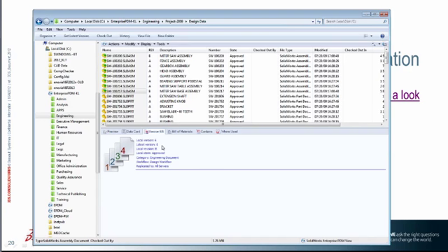The Version tab just gives me some information about what I have in my local cache, because Enterprise PDM works on a local cache basis. What that means is that we have a centralized server where the files are stored, and you can have replicated servers if you have more locations throughout the world. But then it brings the data down to the user's workstation when they're working on it. So if you need a file, it'll copy it down to your local workstation. So when you're doing opens and saves in the system, you're doing it from your local workstation.